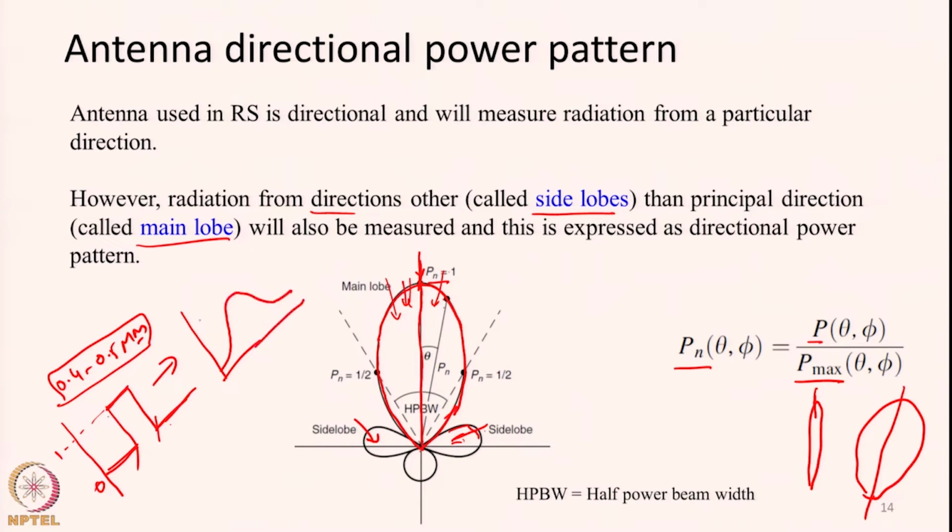Like it may not have a uniform data collection or response pattern within this 0.4 to 0.5. That is why we define this full width at half maximum concept, right. So, this will define 0.4 to 0.5. Essentially there will be a peak wavelength at which peak response will be there, then the response will go off, and the point at which we have half response, the full width at half maximum, we choose those endpoints and define it as bandwidth for that particular sensor.